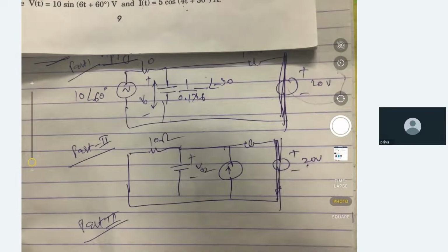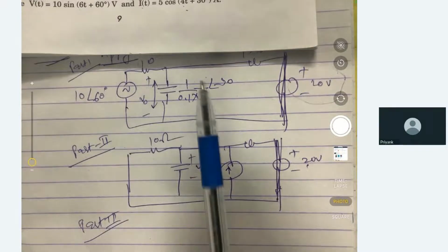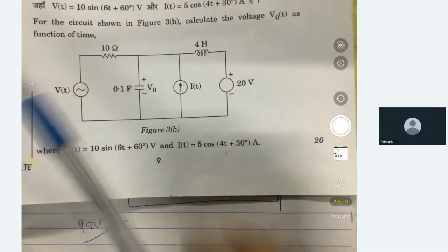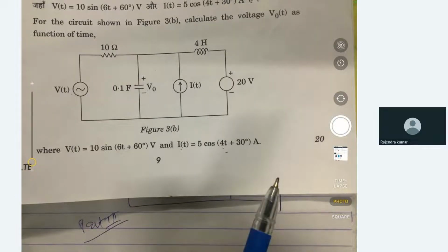And what if we do that, would nodal analysis be much better in this case? Why can't we do nodal analysis also? Yeah, we can do nodal analysis also. But here we have DC sources as well as AC sources, and in that case, we have to apply the superposition theorem. The frequency is also different, and these components are not fixed. They will change with frequency. They behave differently for different source frequencies. That's the critical thing. Yeah, I got it. For different frequencies, superposition would be the best way. Only that approach, yeah, best way.